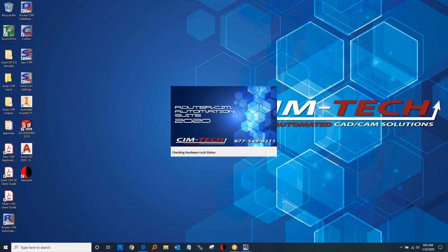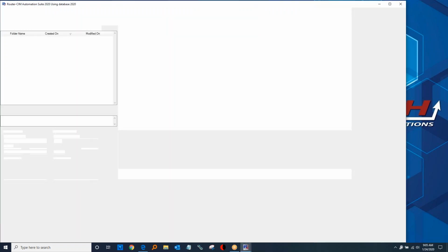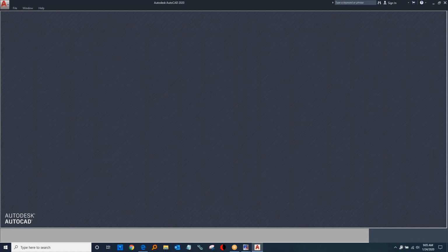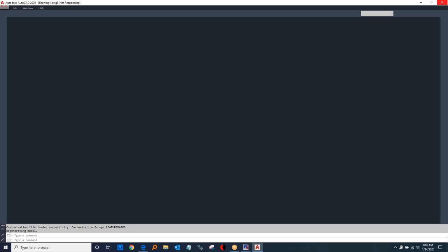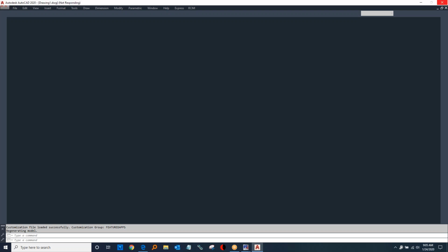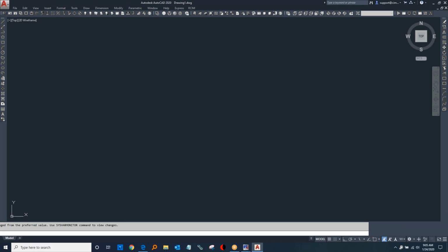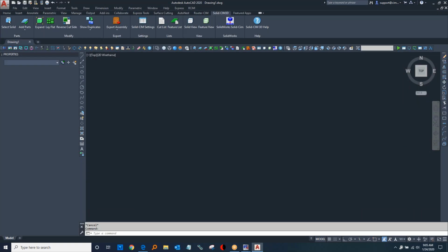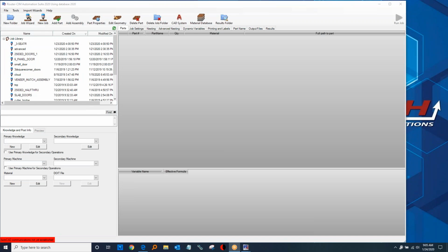It knows the name of the part, how many, and what material, and the layers tell it what type of toolpath to be on. So anything on layer cutout uses a 3/8 tool, for example, at inside cutting at 500 inches a minute. And dados maybe use a 1/4 inch tool number 3 at 350 inches a minute. Outside cutting has a different knowledge, and drilling's a different knowledge. Once these machining knowledges are set up, you wind up using those over and over in all your jobs.